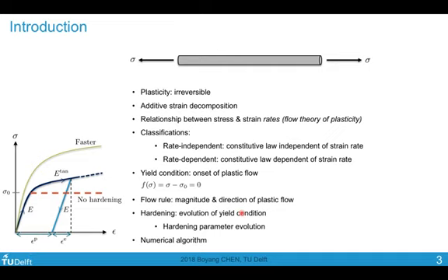We need a numerical algorithm to accurately calculate the incremental strain and the decomposition of this incremental strain into elastic and plastic parts, and the incremental stress and the tangent stiffness. Then we can make sure that in every increment we achieve equilibrium.